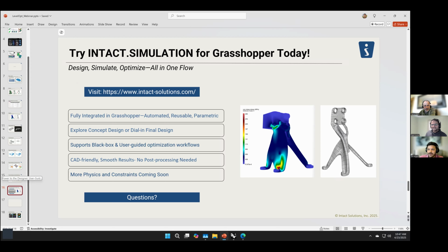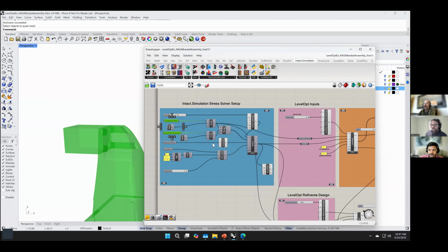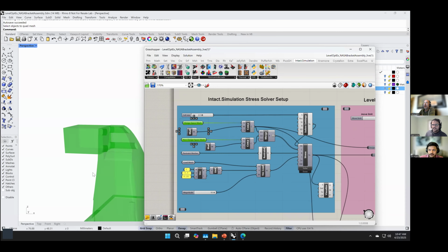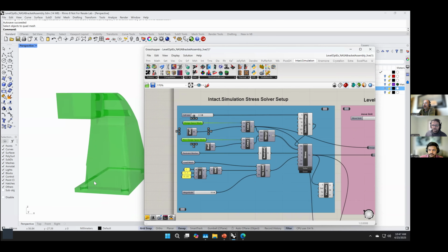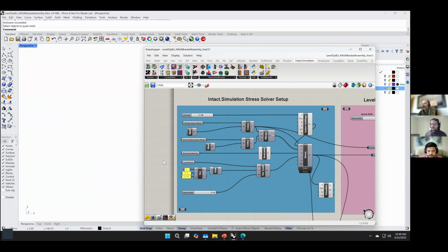How do we define the right grid size? For simulation, usually you can define the cell size based on the features you want to capture. So if there are holes and bending members, and you want a certain number of cells through those to make sure that the behavior is captured accurately, you directly describe the cell size. So that's how you do that.